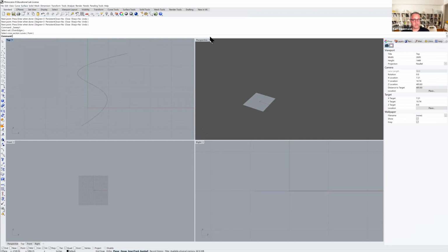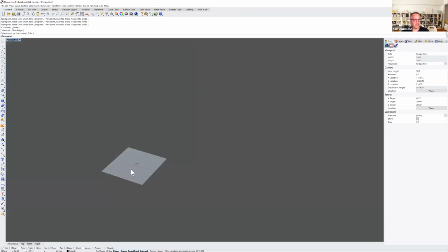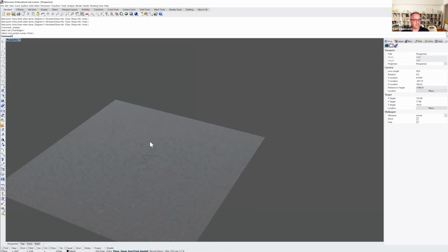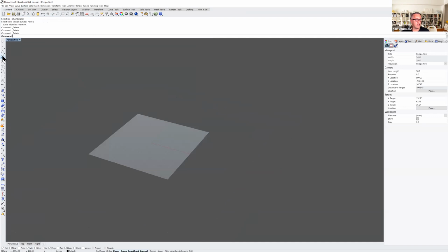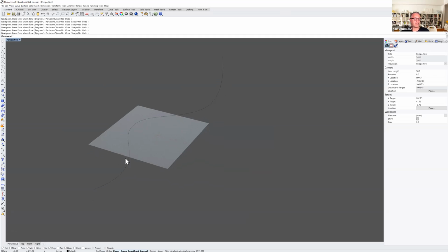So here's a good way to reinforce a C-plane or construction plane. Let's maybe do it at a different scale. I'm going to draw a big, just kind of meandering curve in plan. What it wants is, let's extrude something along that curve, like a handrail or something that's just a kind of round shape. But in order to draw that round shape, we have to do it perpendicular to that path.